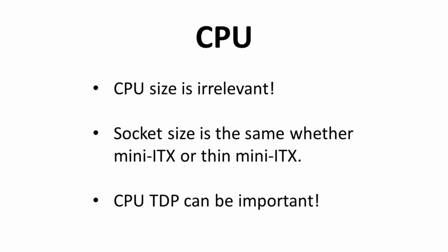Next component, the CPU. The CPU is not a concern from a size perspective. The socket for a mini-ITX or thin motherboard is the same. There aren't small CPUs for a given socket. There are, however, higher power CPUs for a socket. Power is relevant. Power delivery is relevant, and the cooling consequences are also relevant.